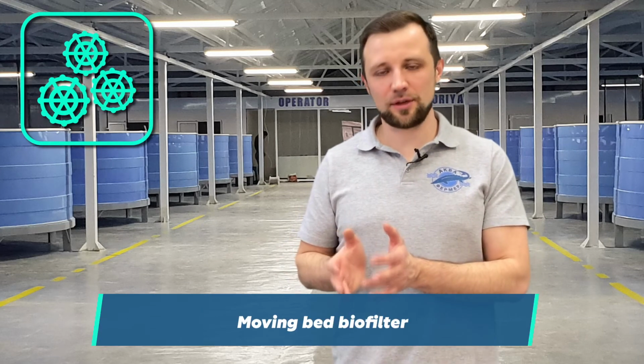What kind of equipment would I recommend for a sturgeon RAS farm? Well, I have already told you about the tanks, what size and depth they should be. So now the primary issue is water treatment units. The first is a drum filter. The second is a moving bed biofilter. I will honestly say that I am an advocate of the moving bed biofilter because it's very stable, easy to operate, and it also provides water degassing, and I am convinced that it has a serious advantage compared to other biofilter types. Next is a fixed bed biofilter.